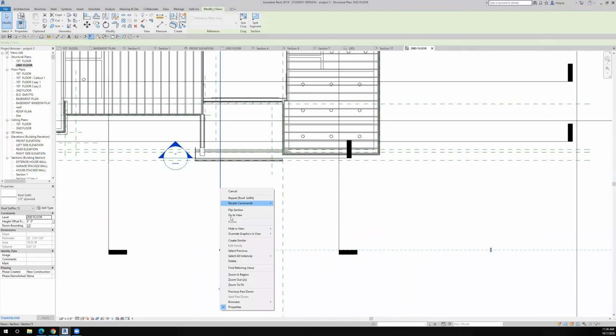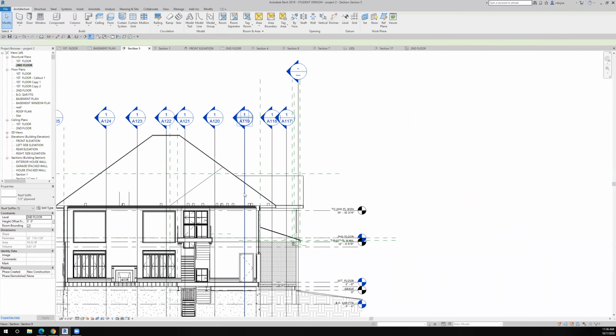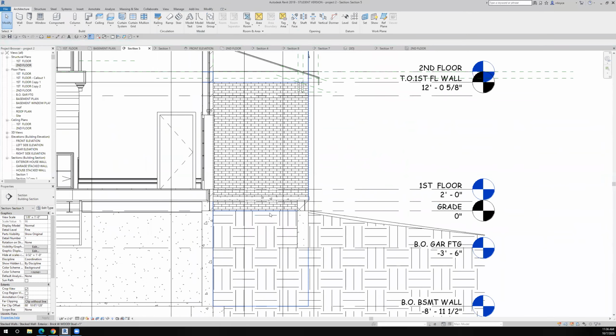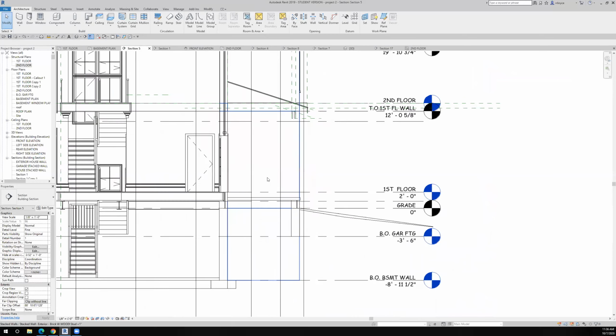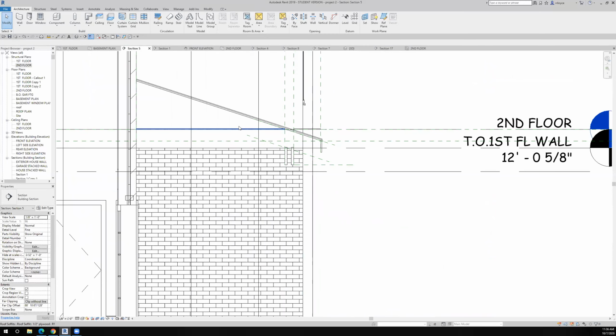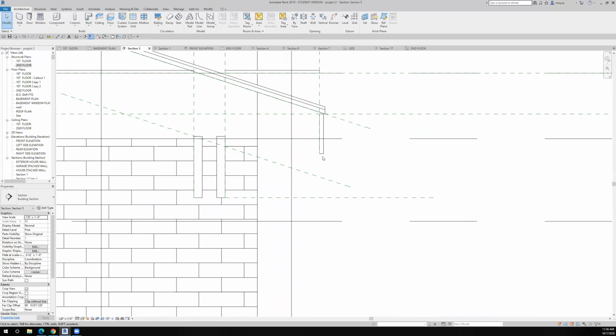Now we go back to this section here. And I'm looking for the roof or the ceiling, which looks like that's a floor in the background. I wasn't paying attention to where, here we go. There it is right there. So let's see if I can use the align tool now. I want to align with, actually no, I want it to be a ½ inch above here.